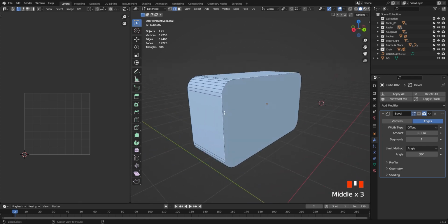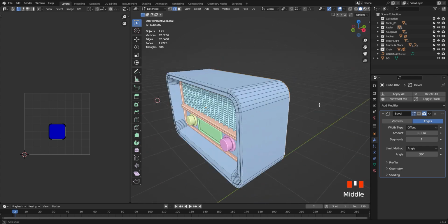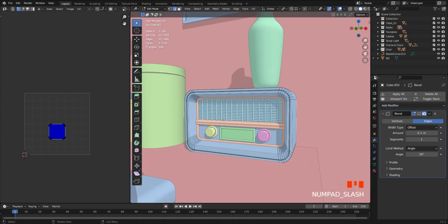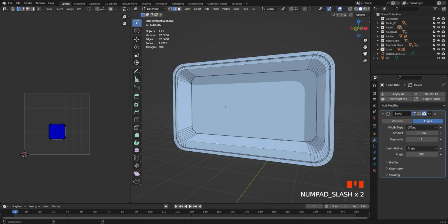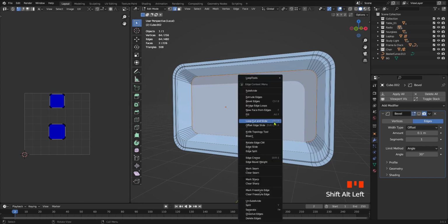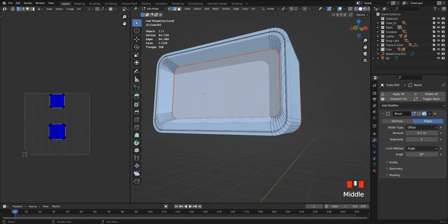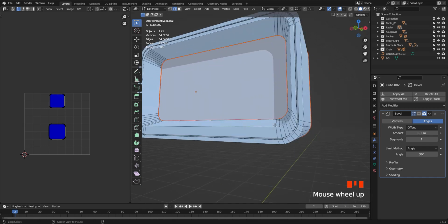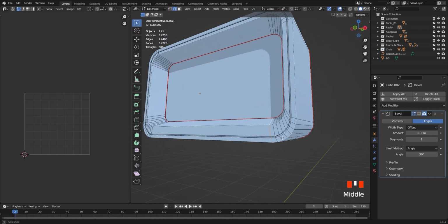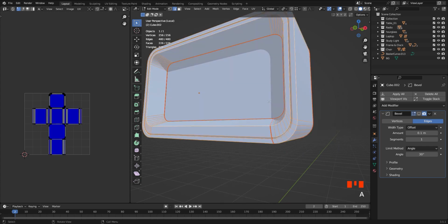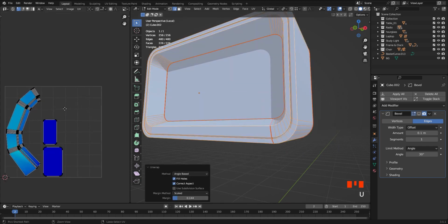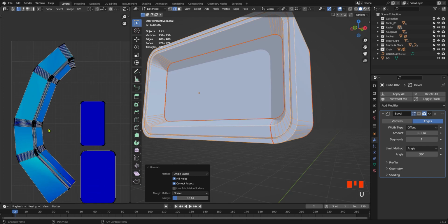Unwrap the outer part. The process is similar to cylinder. The back face and the one inside also on the opposite. Add marquee. Connect them from one of the corners. Then right-click and mark it. Press U to unwrap. The map is almost impeccable. There are no issues.